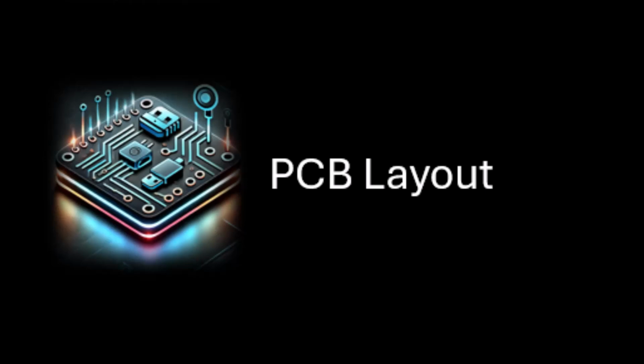You look at where your connectors go, you place them first, and then you place all your other components to fit around these mechanical constraints, which I talked about earlier. And then you do a check in the end to see if you satisfy the basic requirements set forth by manufacturers. For our USB-C to headphone jack adapter, I'm guessing a two-layer PCB would be sufficient. But yeah, we can go into more detail, and this is going to be part of another video.